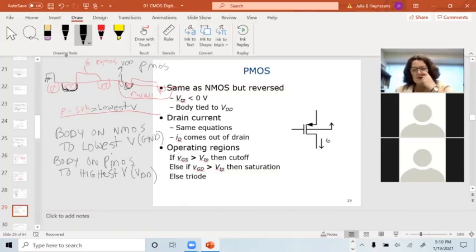And in the lab, we use the 4-terminal transistors and Mentor Graphics. So you have to actually physically draw wires to those bodies and make sure the NMOS bodies are all tied to ground, the PMOS bodies are all tied to VDD, otherwise your circuit will not work.